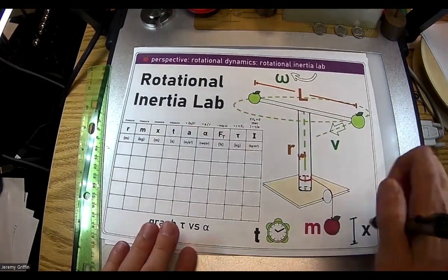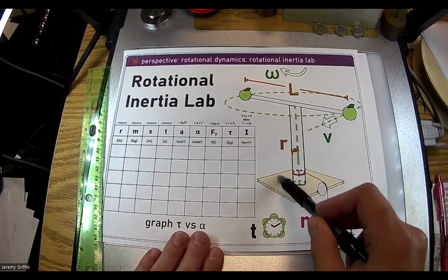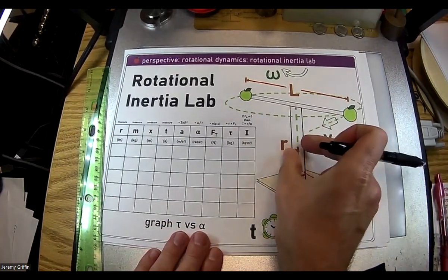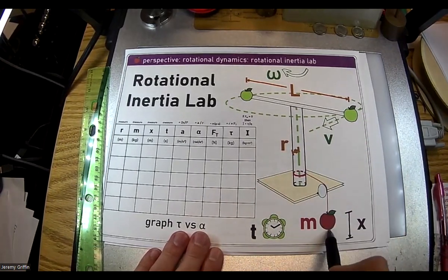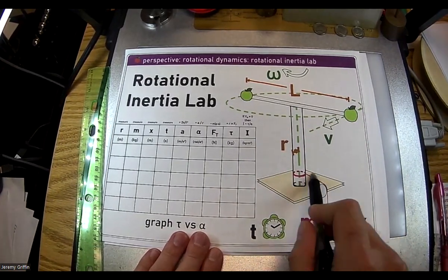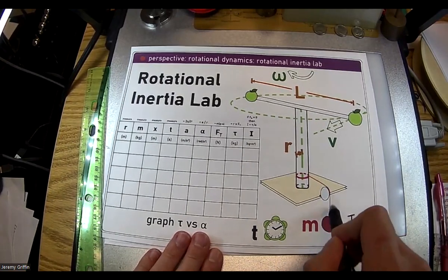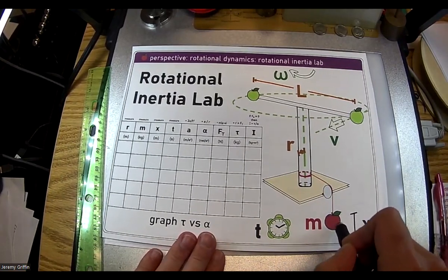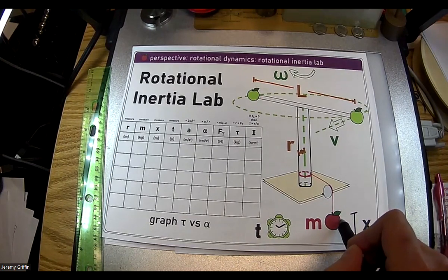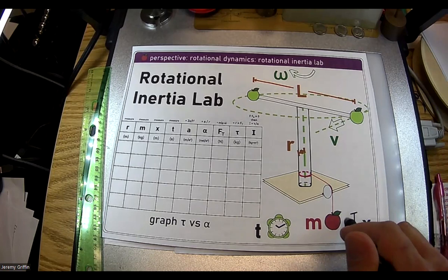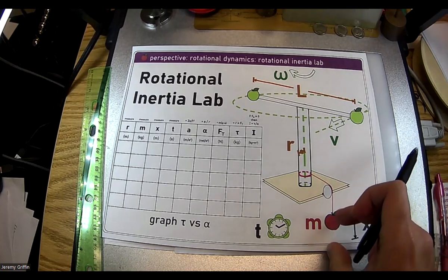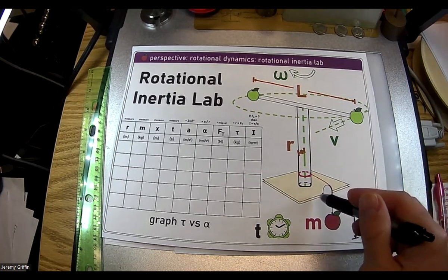That's rotational inertia. What we're going to do is wrap a string around the central pipe, which has this radial size r. That's going to be important. Throw a weight over this pulley, and the weight pulls down. Now the tension in the string is a little bit less than the weight that's hanging down. You'll see that idea later today, and we're going to recap it. If it accelerates pretty slowly, the tension's pretty close to the weight, but a tiny bit less, and the more it's accelerating, the more slack in the tension.